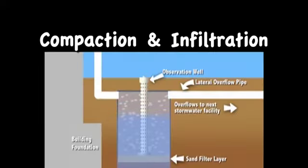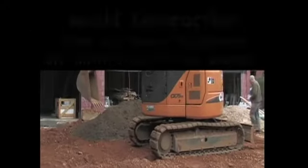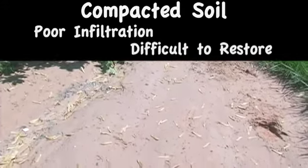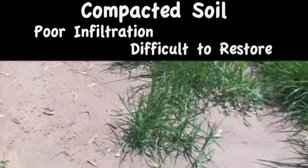When constructing an infiltration device, we also consider soil compaction. Soil compaction occurs when weight is applied to soil, causing it to compress and ultimately reduce pore space. Compacted soil will not infiltrate water properly, and restoring pore space can be difficult.